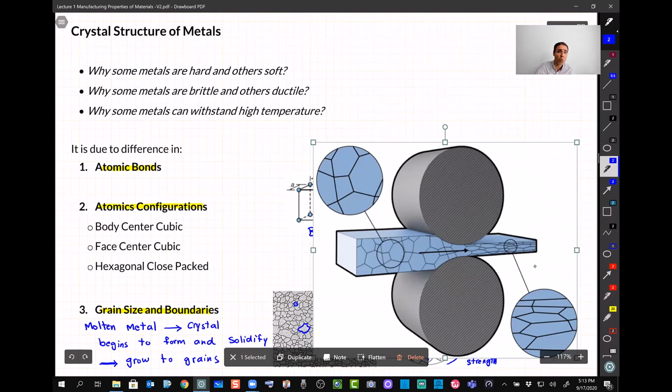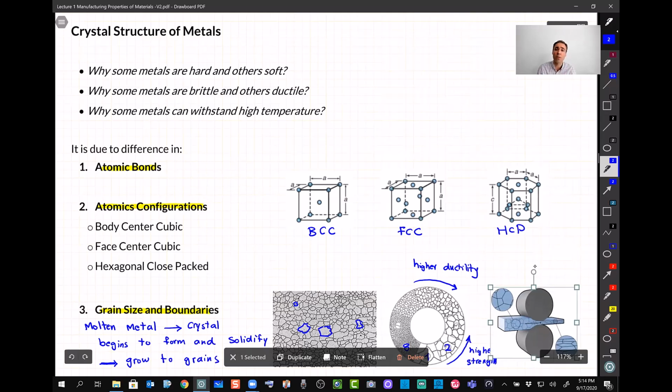The same process, like in forging, the same things may happen, which when we get to the forging process and rolling process, you will see, and we have formulas to calculate and estimate how the modulus of elasticity and the strength of the material may change because of these changes. But the short answer to your question is yes, the property is going to be different in X and Y because now the grain entanglement and the way that the grain has been put together is changed. But how we can quantify it, we leave it until we get to the module for forging and rolling process.